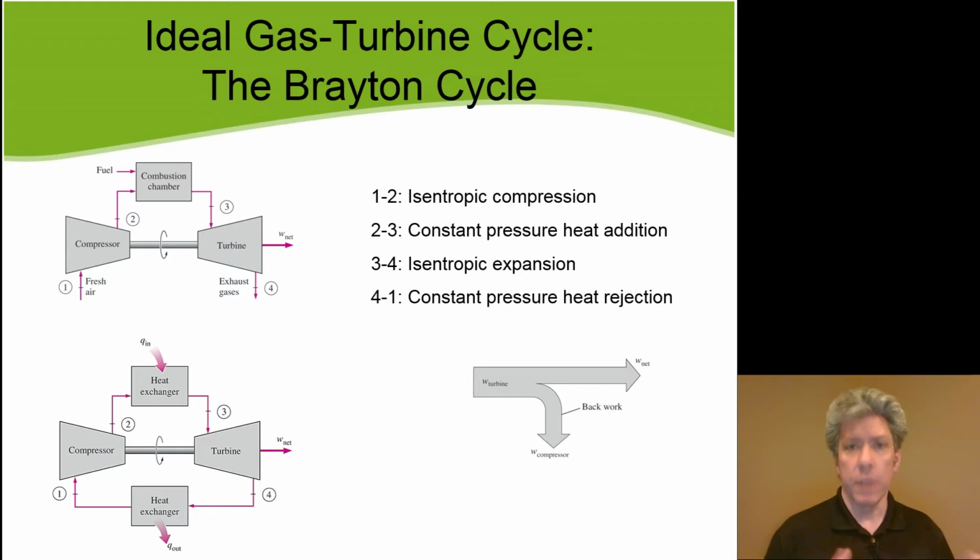In a regular piston cylinder engine, the way things go is that a piston that is on an expansion stroke can be used to drive a piston that is on the compression stroke. And of course, the piston on the expansion stroke produces more work than the work required to compress the next charge of fuel and air mixture. So in this case, the turbine is driving the compressor, and there's enough work left over to extract work from this engine and have a net generation of work from thermal energy.